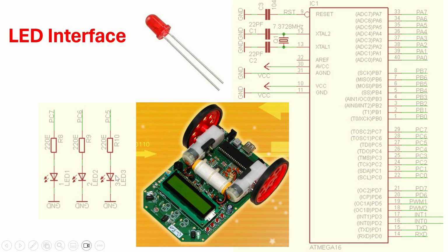However, there is a problem here. We are talking about the voltage, how much voltage you should apply to make it forward biased. But the other important point is the current. The amount of current flowing through this LED decides the intensity of the light, because finally the current is converted into light, photons.